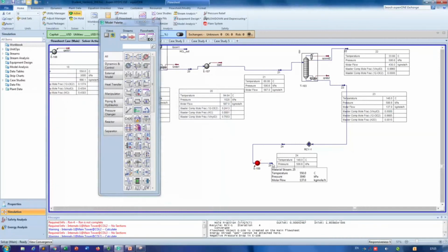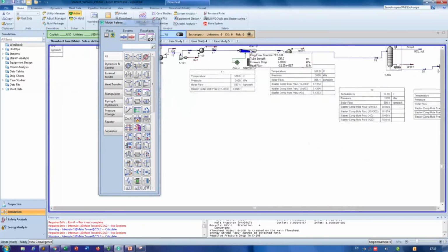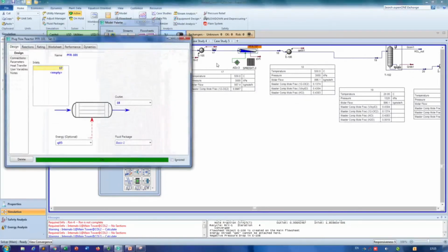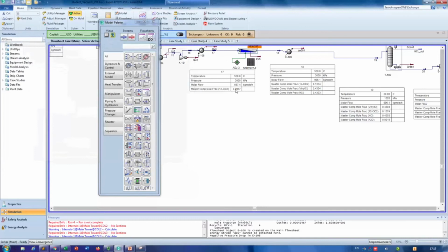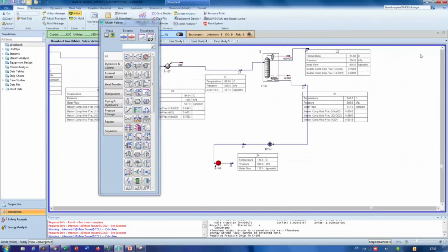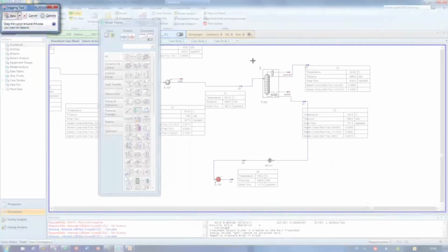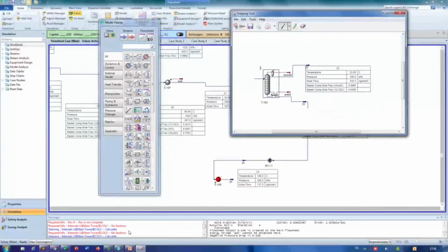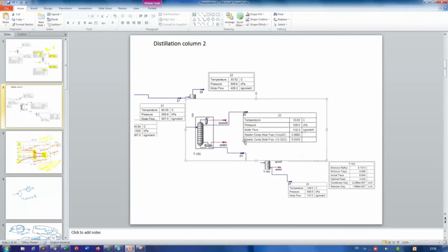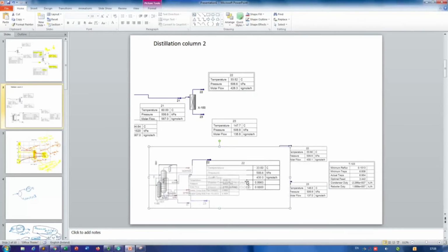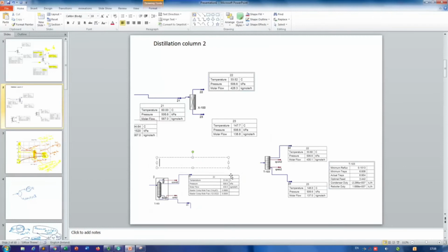So everything is converged. So what we are going to do is connect this stream 25 to the plug flow reactor, or the pyrolysis chamber. So now everything will be fine. So double click. If you see here the inlet, stream 17 has ethylene dichloride. So we are going to add a few more ethylene dichloride, which is recycled from this stream. Also have a note of this value, molar flow rate 430. Maybe I can take a snapshot of this before recycling. Okay, so this is before recycling.